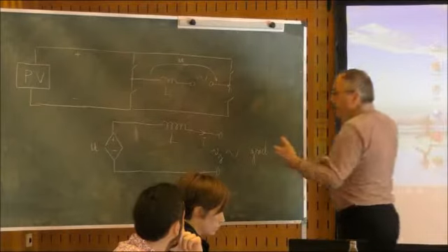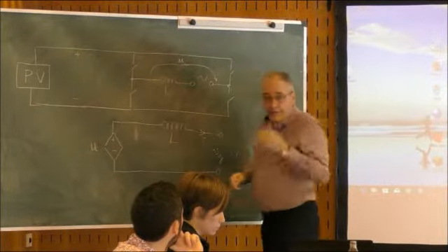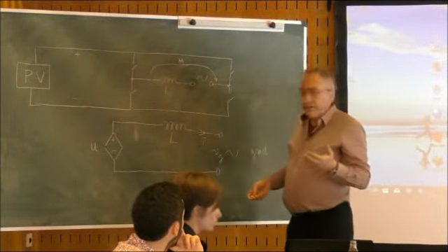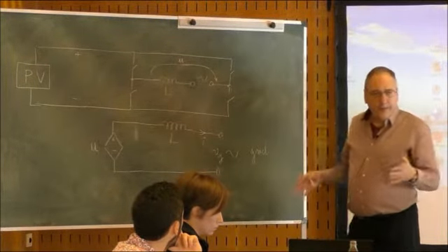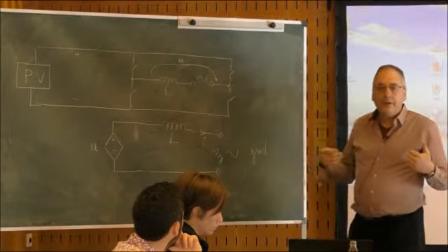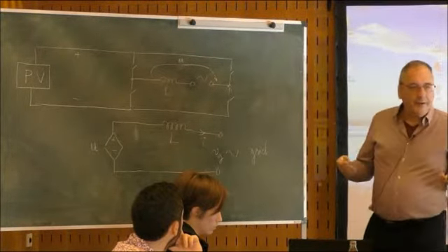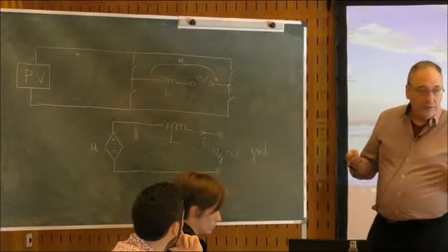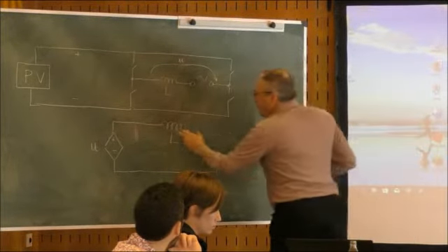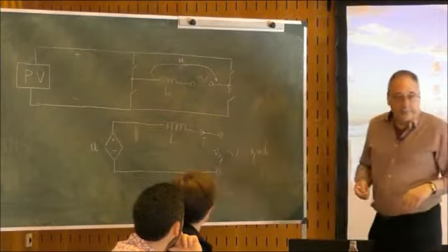So there must be something to separate the two voltages, and people put an inductor, because the inductor not only separates the voltages, but it does not consume energy. An inductor is a purely reactive element, meaning that on average the power that it consumes is zero. And so we need such an inductor to separate the two sides.